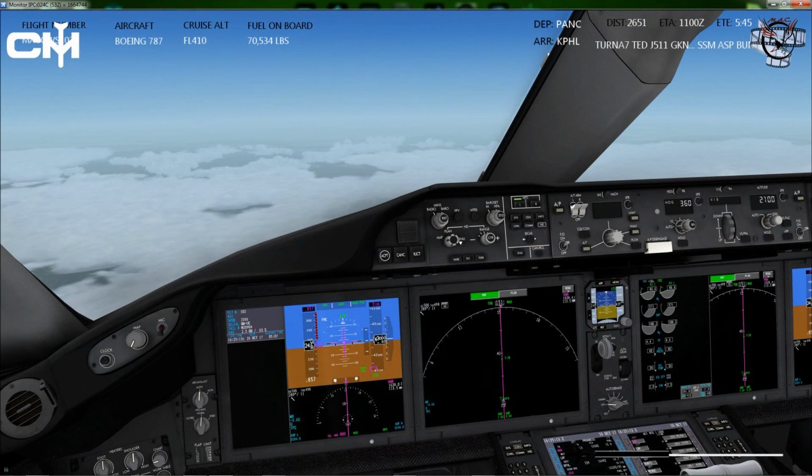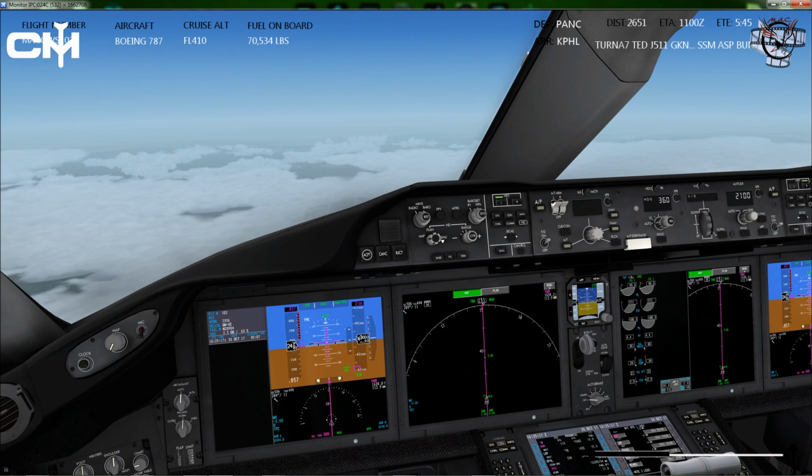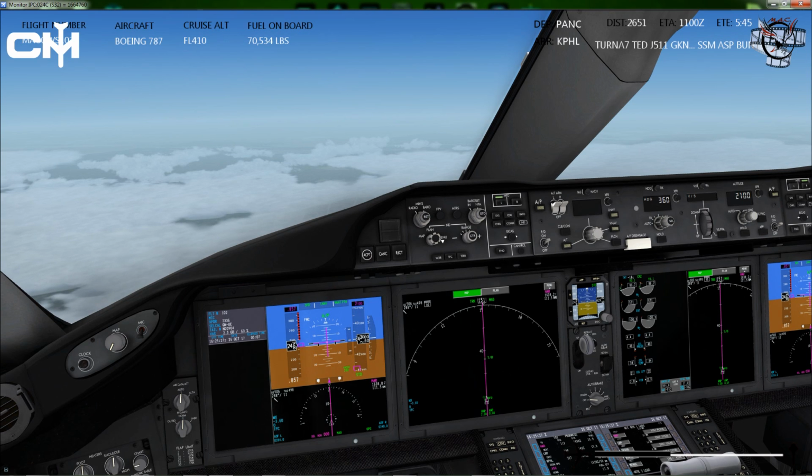All right, so it seems to be recording just fine, so not worried about that. But anyway, the point I was getting at is we're not using ATC, so obviously we're just going to set our altitude either at our first altitude restriction that we know about based on our arrival, which we don't have any on this one, or at the altitude for our approach, which in this case is, I believe, 2100 feet. So that being said, let's go ahead and take care of our descent procedure. We want to hit the recall button.